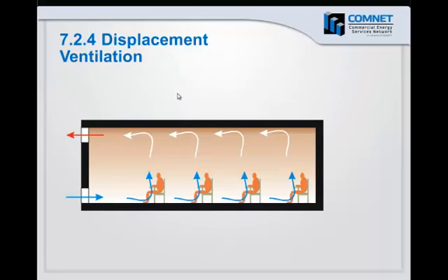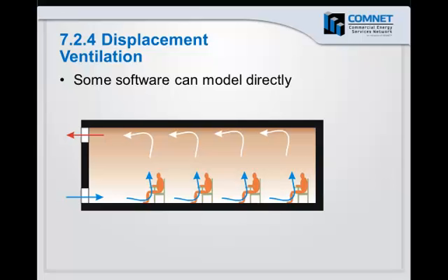Displacement ventilation is a technique that we've promoted for schools and other applications. It's been used in Europe for decades. The air is introduced near the floor at a warmer temperature, and it rises, and you create a stratification effect. So it has a number of energy benefits.